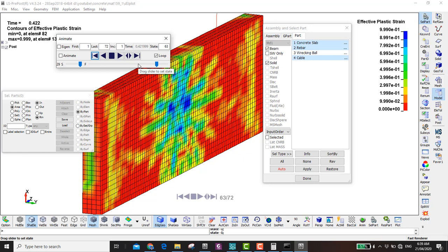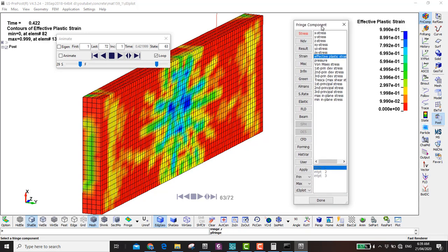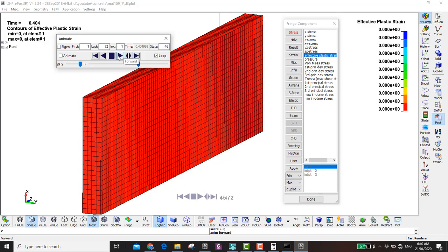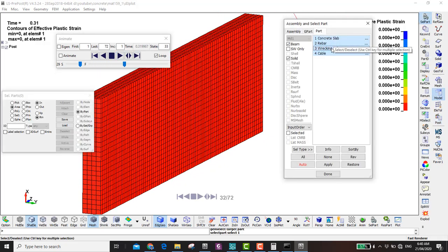When we use this material model, the seventh output, you see 1, 2, 3, 4, 5, 6, this 7 is not actually the plastic strain. This one refers to the damage in the concrete, 0 meaning no damage and 1 meaning full damage. What is the damage model? I don't want to get too much into the theory, but you can read the theory manual if you are interested. So this is our simulation for today.